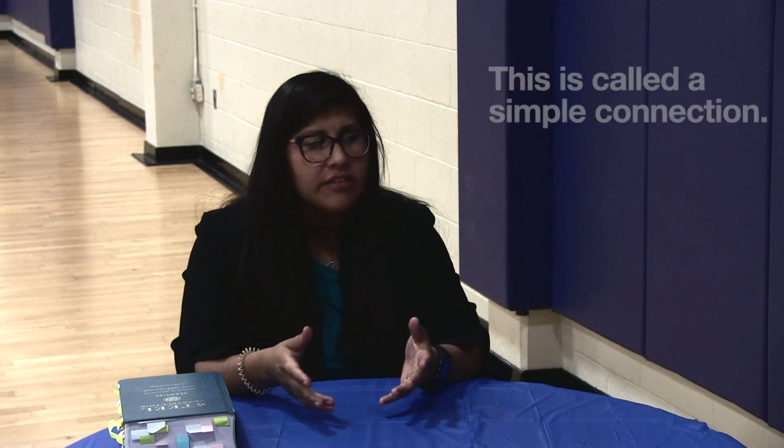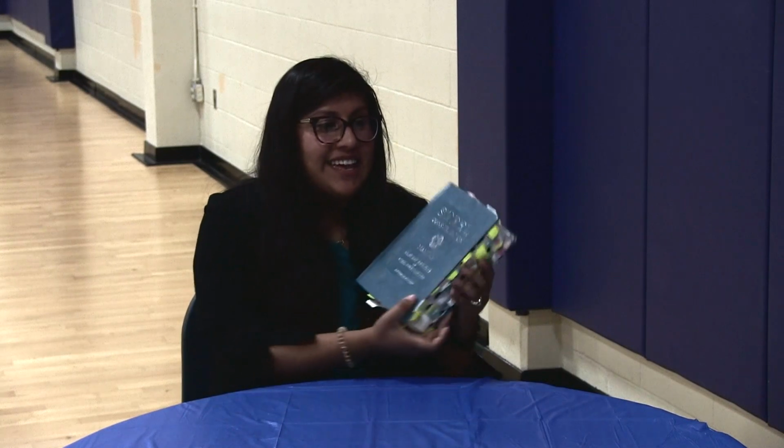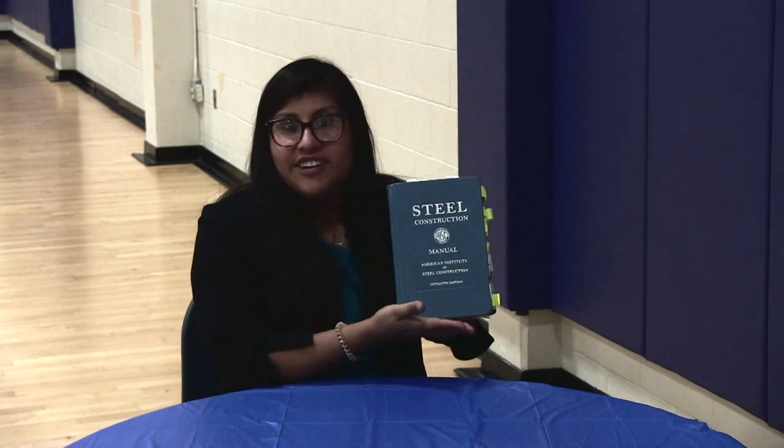I am assuming the force acts directly on the bolt rather than loading eccentrically. Bolt failure is outlined in AISC chapter J3. We will focus on J3.6 for bolt shear strength and J3.10 for bearing and tear-out strengths. Let's assume bolt spacing and edge distances are not a concern.